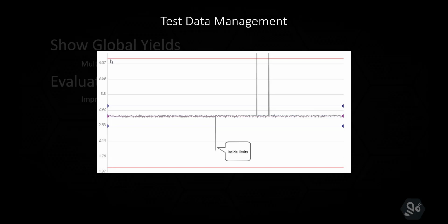You can see your limits as these red lines, and you can see the data variations coming from the different units. You can see that a couple of these guys are failing against the higher limits, so we'll be able to trap those. But in this case, the limits are so wide that it allows for these outliers to be hidden in the data set. So having a lot of these could indicate problematic products and quality concerns that you will experience later on.